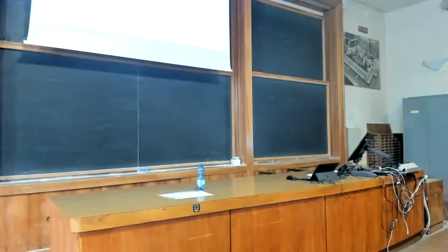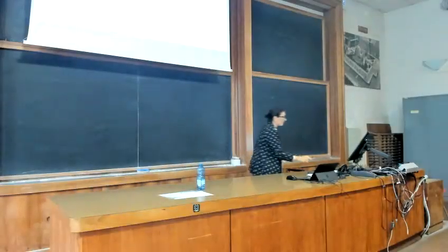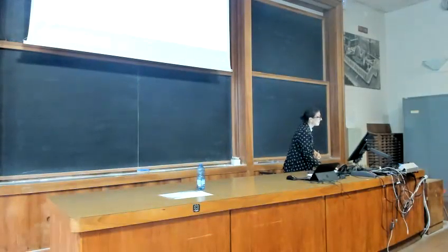You do not have the unit weight of the soil as input data, but the density. In particular, for the first strata of gravel, have a look at the picture. You have the dry density, because looking at the picture, you immediately see that the groundwater level is here. It's 3 meters deep here.